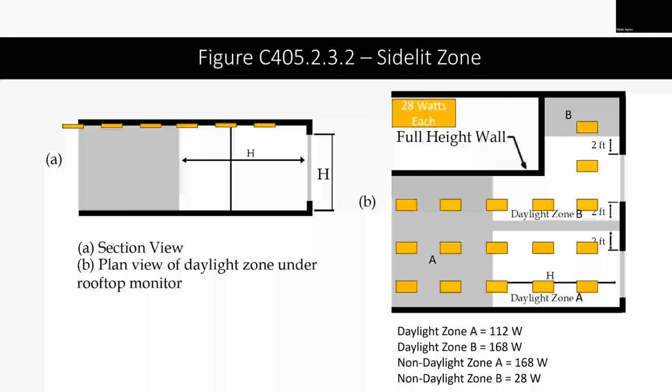Oh, but you would be maximizing your daylight harvesting area. So if you're going for any incentives from, say, Idaho Power or something, that's a benefit. I mean, you still get the same amount of area, 2 feet on either side of the window. Yeah, but you could theoretically fit a whole extra daylight zone depending on how the space is arranged. Like if it's an open office, a continuous area, and you want that entire area. But that entire area can be all controlled together anyway, for the same cardinal direction. Yes.